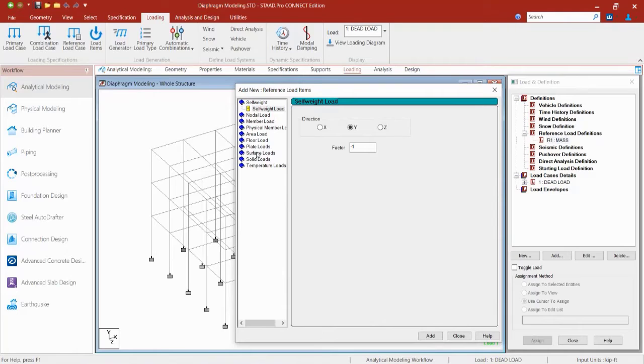So joint moments that are entered will be considered to be weight moments of inertia. And additionally, you're going to enter them considering two things. First of all, you're going to typically enter a consistent sign for all of the masses within your structure. I typically enter mine all with absolute value format. The reason this is important is because you want your masses to all be added together. If you have inconsistent signs, they may eventually cancel each other out.